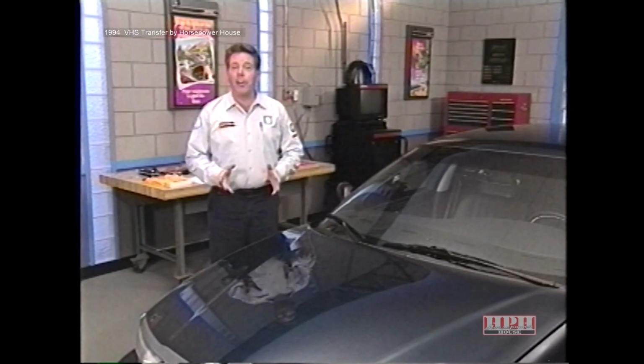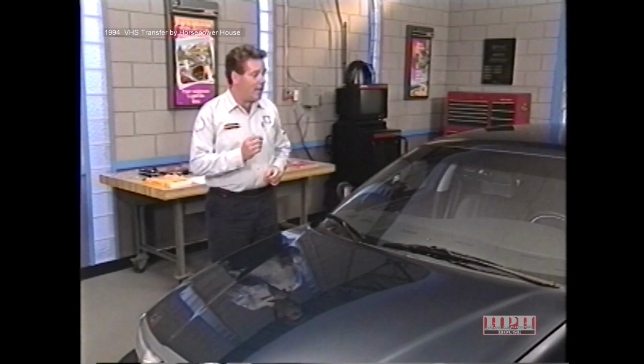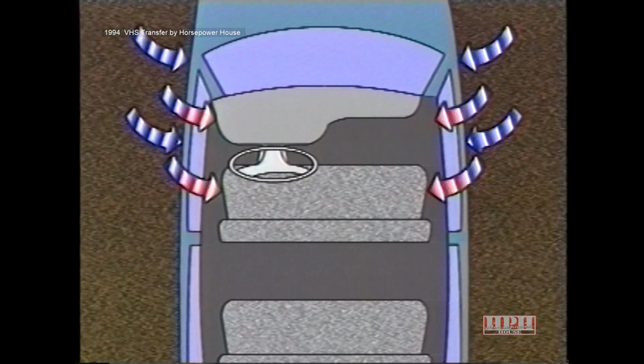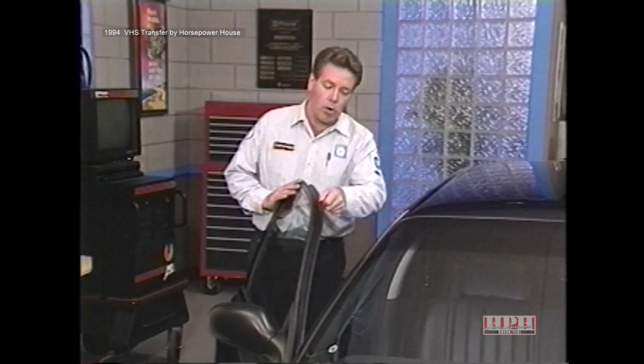air leaks are not caused by air escaping out of the vehicle, but by air seeping into the vehicle. The situation can occur when the pressure on the outside of the vehicle is greater than that on the inside. Air, and possibly even dust and water, may seep into the vehicle through a loose or distorted seal.